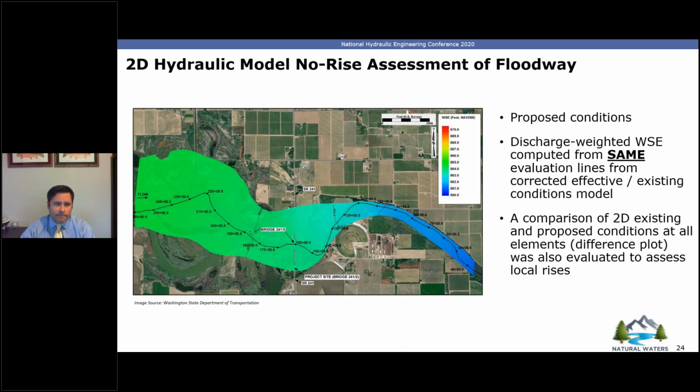That's a good point. I would put that into more or less best practices. So I was mentioning the sensitivity analysis on the locations of the domain. Other sensitivity analyses that anyone should run, irregardless of the type of 2D model being ran, would be mesh sensitivity and Manning's N sensitivity.